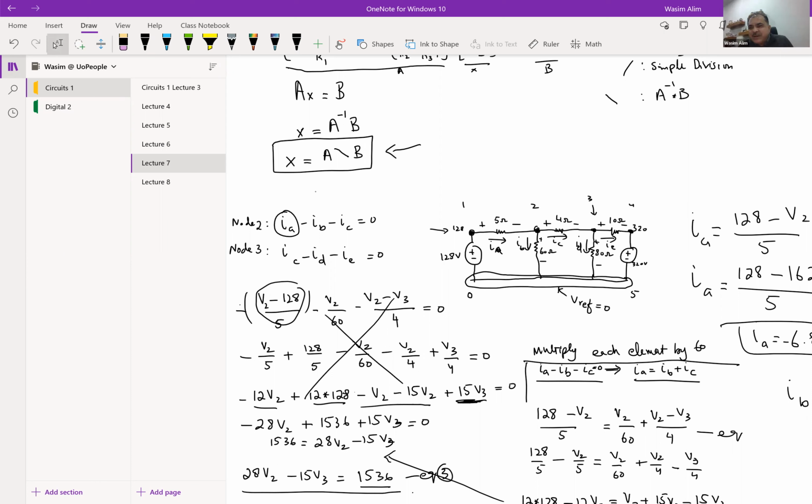A voltage source, a current source, and... Well, that would be... No, I know. So I know that that's a node, but I guess more so for the node voltage equation, you want to start off with the independent node. Yes, that's a node, but I need to find the independent node, which is a node not touching a voltage source or whatever.